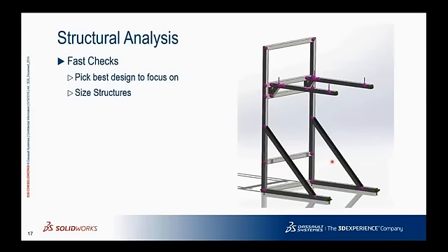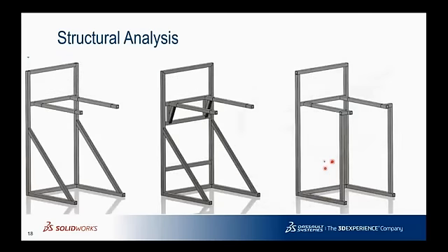Now, a lot of structures contain weldments, whether it's supporting structure for manufacturing equipment or primary structure in off-road equipment. We can use weldments, and in simulation we can represent weldments very quickly and efficiently as beams, which makes it very fast to pick the ideal solution to move forward with from various concepts. And also we can size those weldments to determine what size tubing we need to meet our requirements.